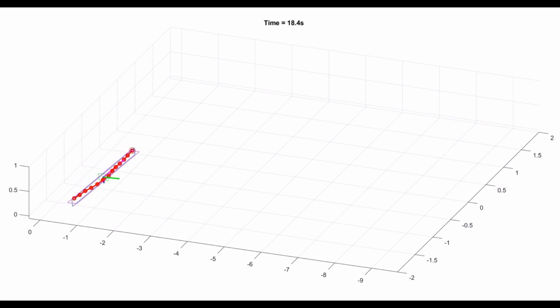The resulting visualization shows the kinematics of the robot, the estimated center of mass position and orientation, and bounding box throughout the trajectory. This is based only on proprioceptive joint data and pose estimate of the head module using the stereo camera and IMU, calculated using the reduced order model presented in this work.